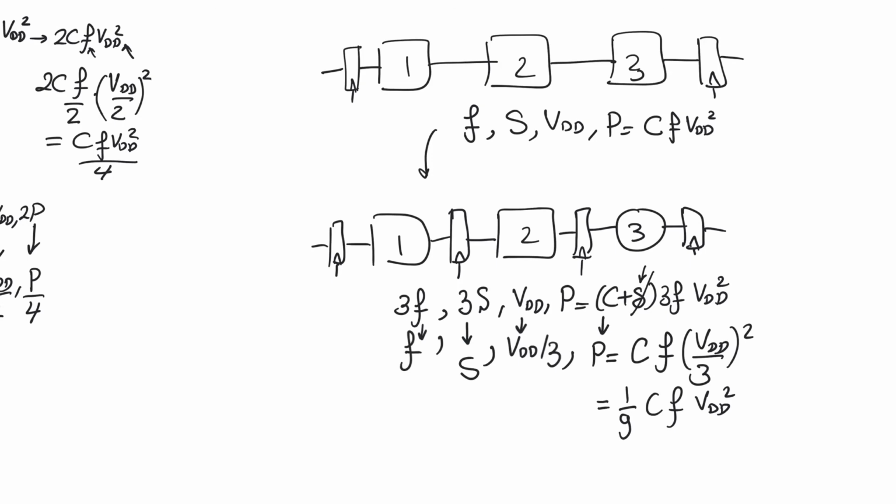We have to be careful about how much we reduce the supply voltage because noise margins are going to be reduced along with the supply voltage. With pipelines, we also have an additional cost, which is the cost in latency, the number of cycles that go by until we see the first output. Latency is not usually a huge issue, especially when you have a latency of a few cycles, but in a large system where the latencies of multiple blocks can add up, this could have an impact, especially on real-time applications like video chatting, for example. So you also have to be careful with the cost in latency.